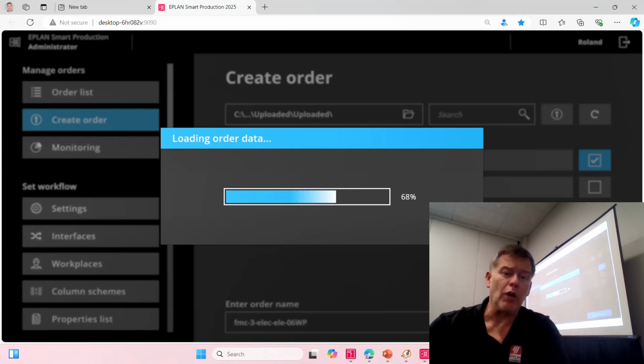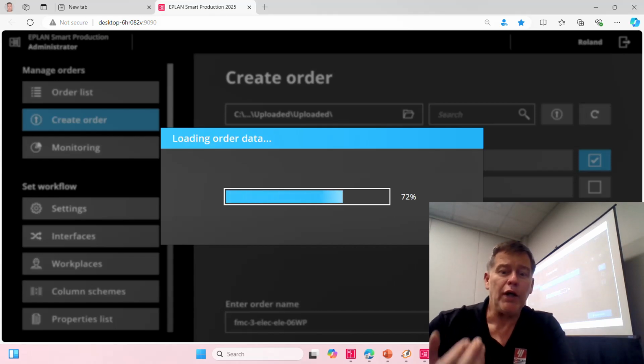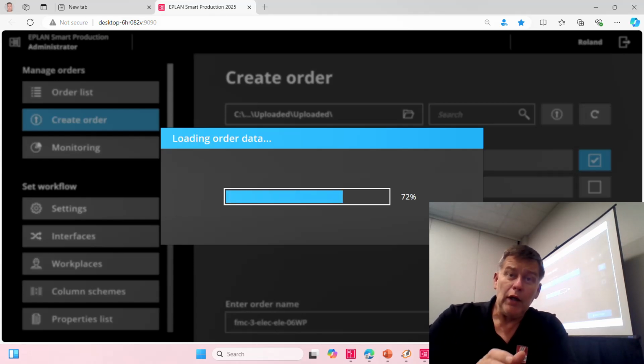Of course, the smart wiring is ideally coupled with somebody that prefabricated the wires, either with a WT or in a manual fashion. In this particular case, what you save is 5 to 7 minutes of cutting, crimping, putting on the ferrules, crimping the ferrules, putting on the labels. So there's a lot of work involved when you do the wiring, most likely up to 8 minutes per wire.